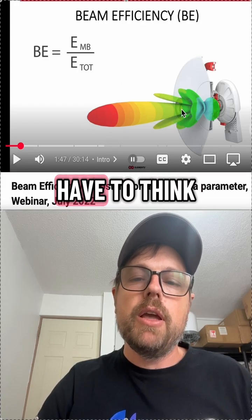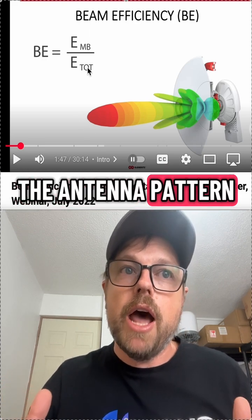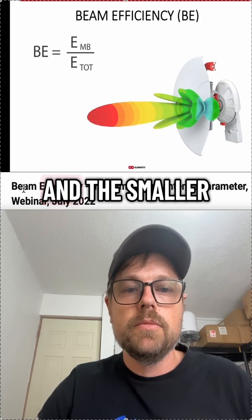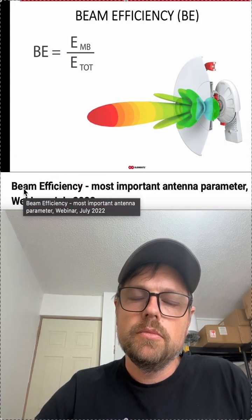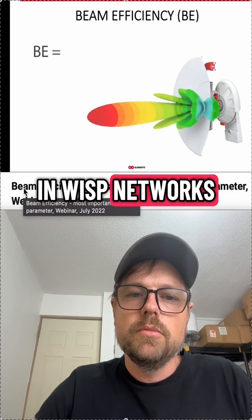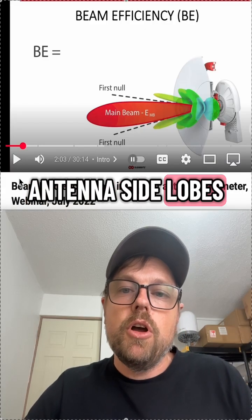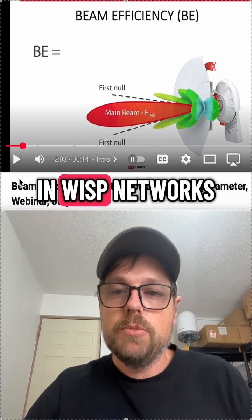So you really have to think about the shape of the beam, not just essentially the antenna pattern, not just whether it's in the main lobe or not within the main lobe. And the smaller the beam efficiency is, the more side lobes an antenna has. Since antenna side lobes are the direct cause of problems in WISP networks, antennas with a lot of side lobes should be avoided at all costs. So he says antenna side lobes are the direct cause of noise in WISP networks.